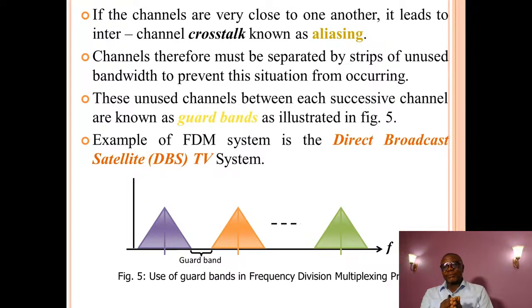Now, look back and see how it is possible. It is possible because when we were dealing with sampling, we said that it is always good to sample at a rate higher than the Nyquist rate. And immediately you do your sampling at a rate a little higher than the Nyquist rate, you'll be able to introduce this guard band.